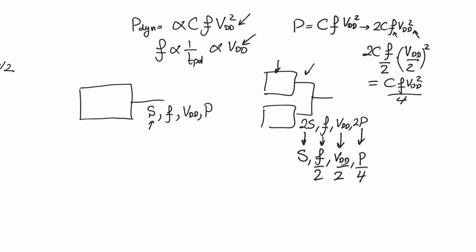But the fact that you managed to reduce frequency had a more profound effect on power dissipation because it had a profound effect through supply voltage. Now, is the price that we are paying only in area? Because if that's the case, why not use 4 of these and reduce power by a factor of 16? Why not use 6 of these and reduce power by a factor of 36? There has to be a fundamental limit upon how much parallelism we can use, the degree to which we can parallelize our circuit. Of course, the cost of area is one aspect, but there's another aspect.